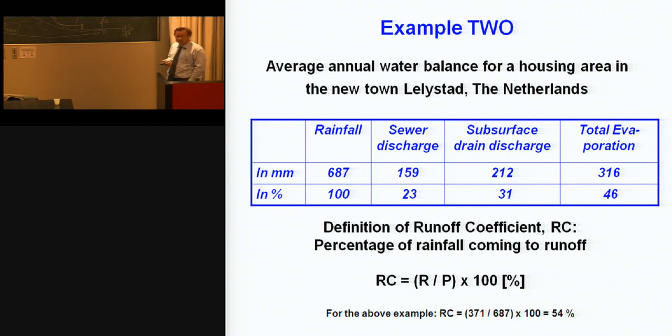The runoff coefficient has to do with the soil surface, right? It's not stable. It has to do with all the hydrological parameters that influence runoff generation. The final runoff is this R, and everything that happens before defines how much this R is. The runoff coefficient is this R divided by the P, the precipitation. All these processes which we discussed define the runoff coefficient. Therefore, the surface, the vegetation, the soil structure, the infiltration and percolation conditions, all this defines the runoff.